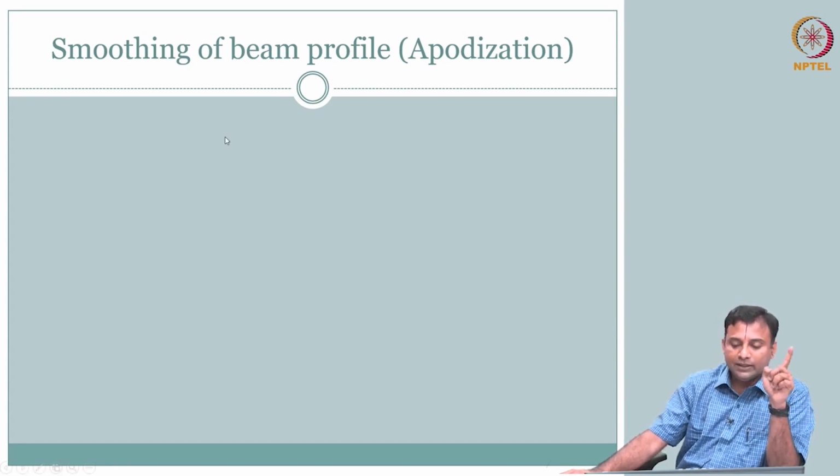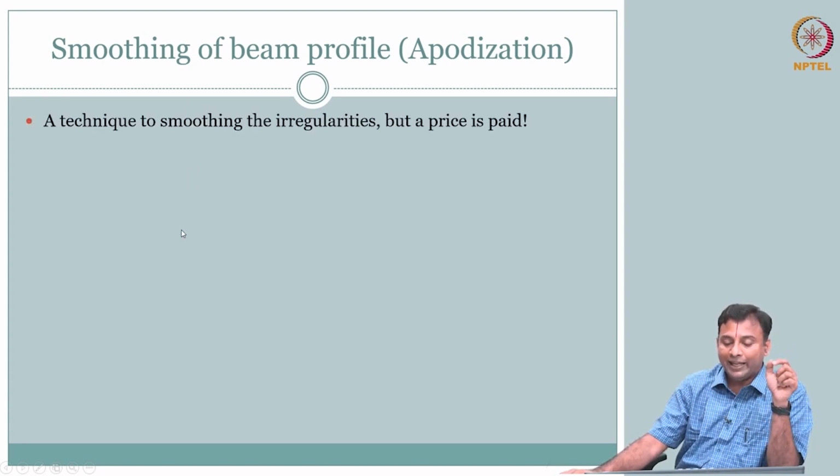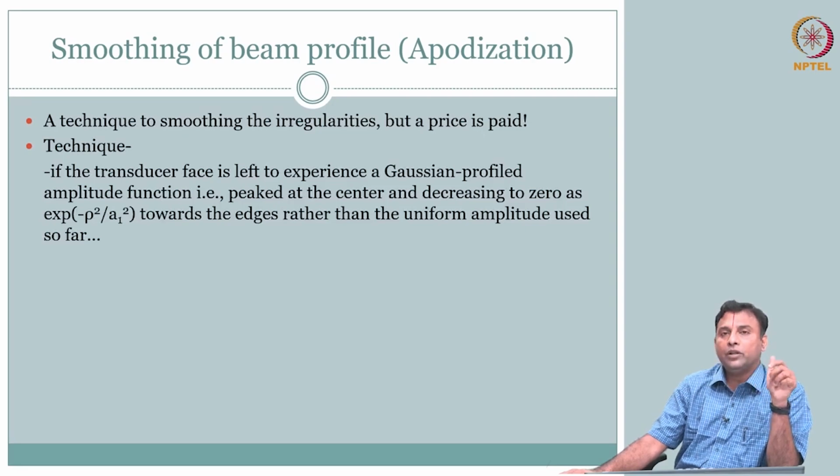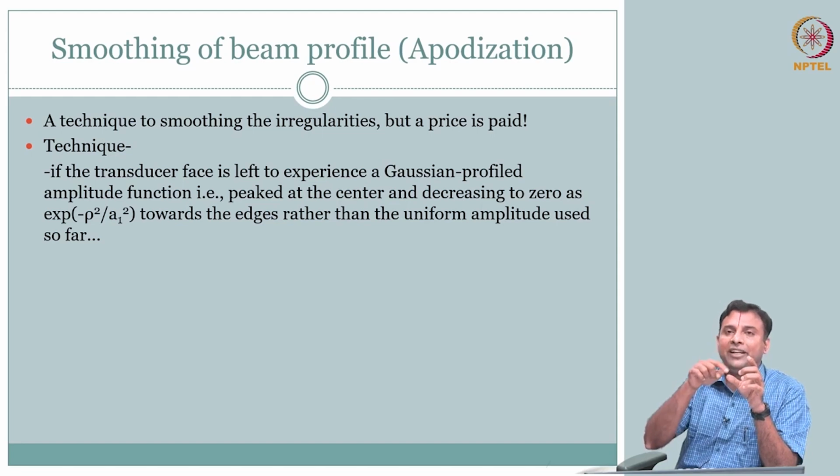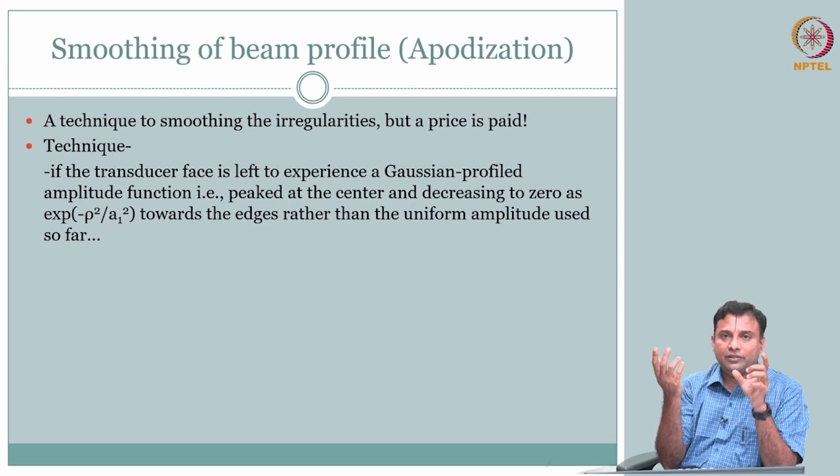Before we do that, let us just complete this beam profile that I was talking about, your rectangular function, hanning, hamming window. You could do that here. What we can do is have the crystal, but make sure that it is not excited uniformly, you have some weighting. The center point gets the maximum weighting. As you go towards the end, you have less weighting, and how much weighting you give can be determined based on your window function.